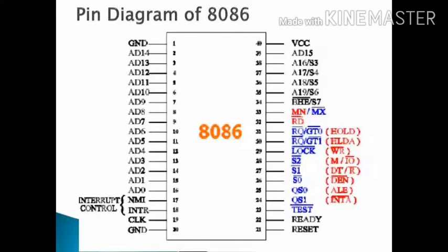If the ready signal is still at logic 0 when the wait state ends, then more wait states are introduced. So it will tell the microprocessor to wait for the next clock cycle, and it receives input from the 8284. That was the clock generator, right, which will be introduced when we talk about the interfacing of this device.